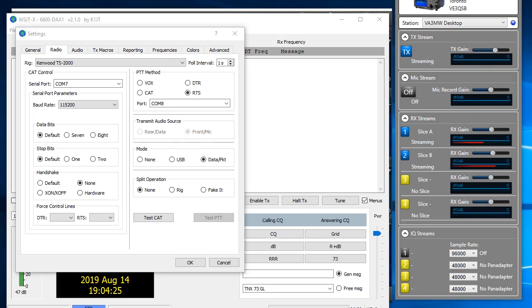So let's talk about DAX. DAX is used to send audio from the radio to your program. Let's focus on maybe WSJT, but any digital sound card program, FL Digi, two-tone, MMTTY, all behave exactly the same way. And the setup is identical for the most part. You have three things to worry about: the audio coming in, the audio going out for the transmitter, and putting the radio in push-to-talk as well. Maybe I guess that's four things. You also have CAT control.